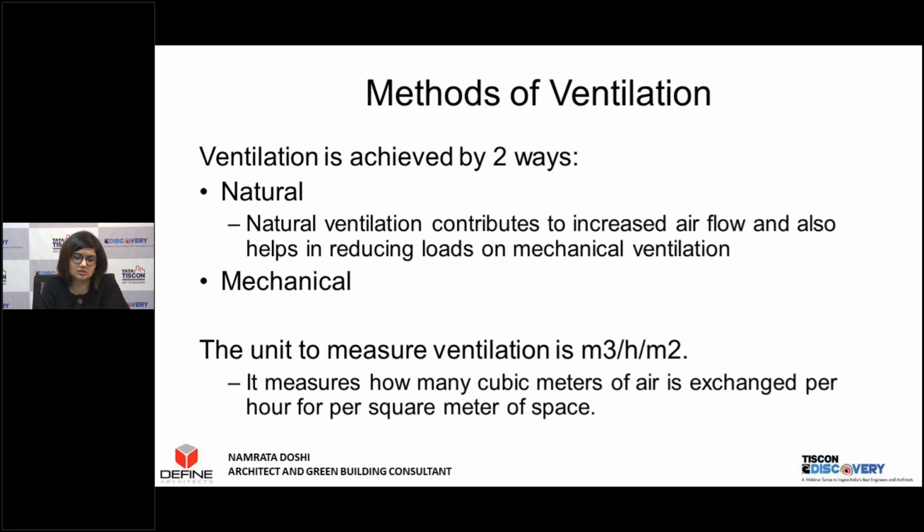Coming to the unit to measure ventilation, in technical terms, it's measured in cubic meters per hour per square meter of space. Cubic meters, which is the volume of air, per hour, which means in one particular hour, how much volume of air am I going to circulate. This is measured against a square meter of space. So essentially, we are taking the space into consideration, time into consideration, and volume of air into consideration, which covers ventilation.